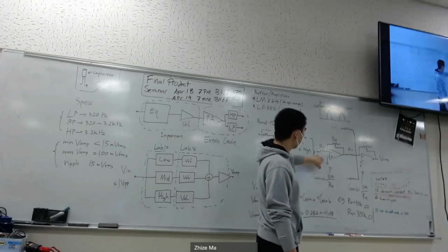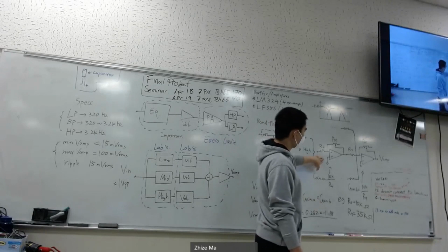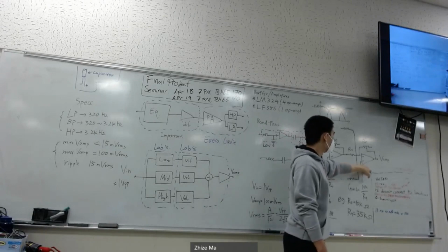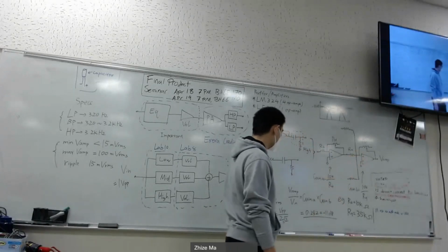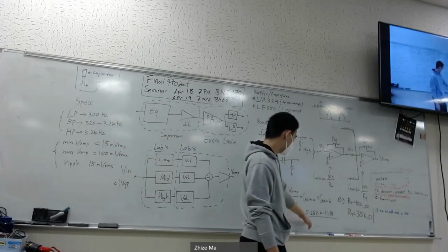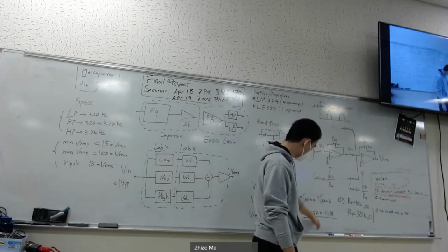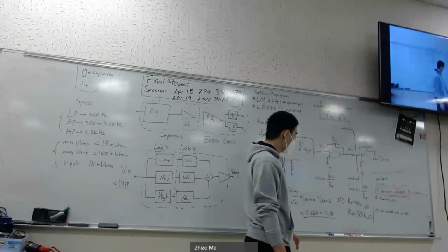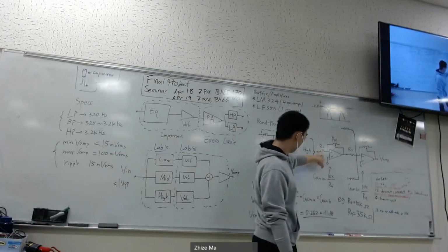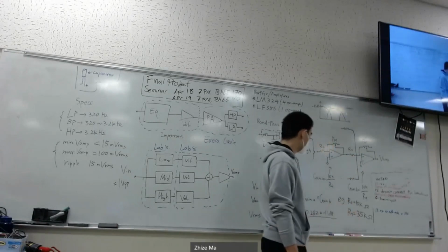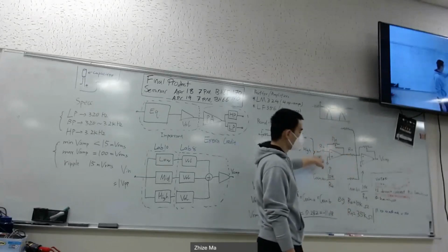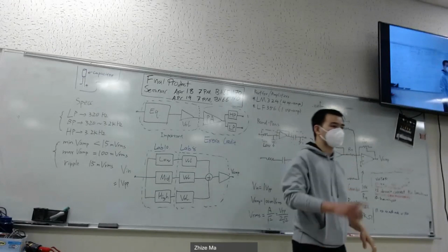Gain A is the gain for the volume control of each pass, and gain B is the gain of the sum amplifier. I did the calculation: gain A times gain B will be 0.282. One example I can give you right now is they can use R4 as 10K and R9 as 13.5K. That's probably the most common value they will use.